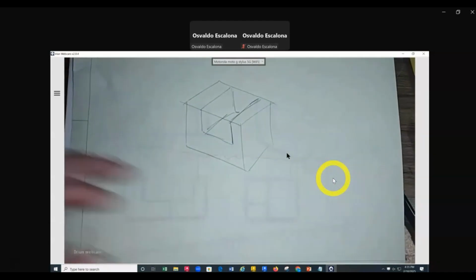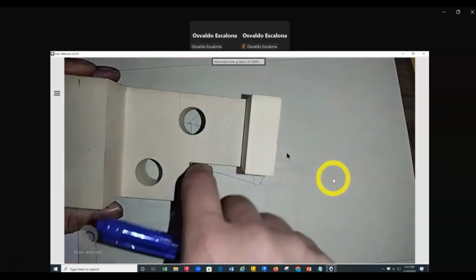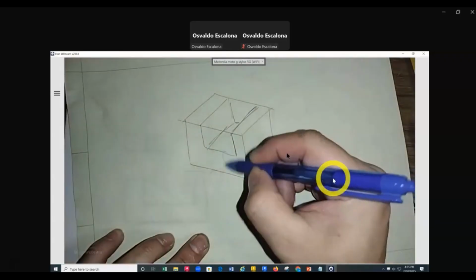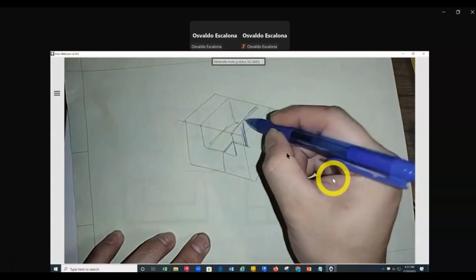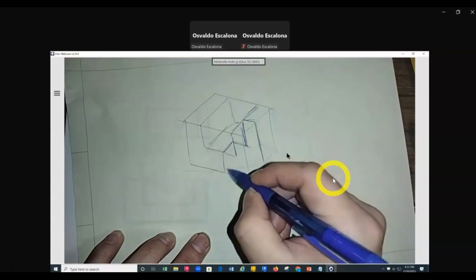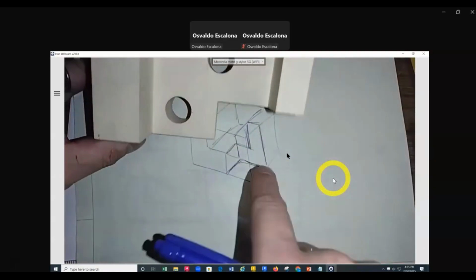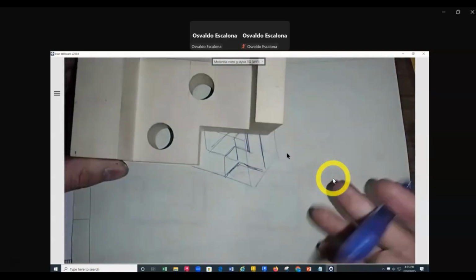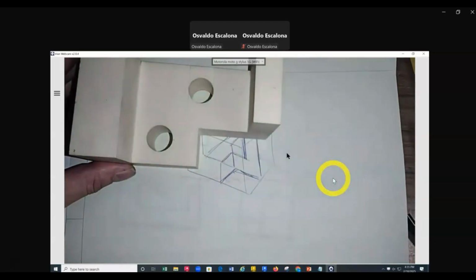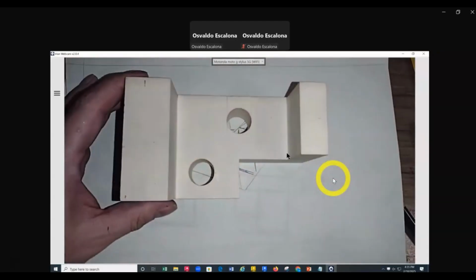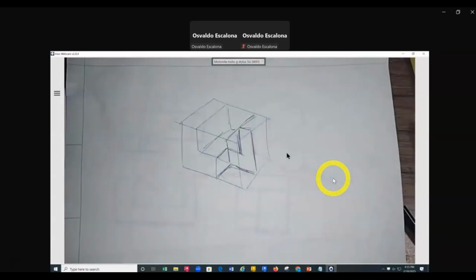Done. Also, it seems to me that here I got another notch, right? See the notch? So most likely after that, I will go down and take away the other one. I went to the top and I will go sideways with my flat end mill and start going like this. Get rid of it, right? And then eventually I will go with my drill somewhere there, and I'm done. All right.